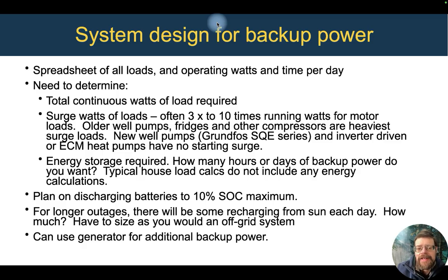So it's when we get into energy storage that there's a new calculation that won't be in your traditional house design. Like I said before, we want to plan on discharging the batteries to 10% state of charge. We don't want to go all the way down to 0%. So we're going to take our rated energy storage of the batteries and multiply that by 0.9 for the usable storage.